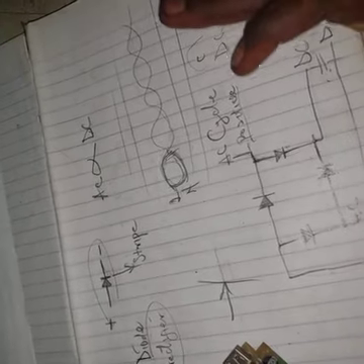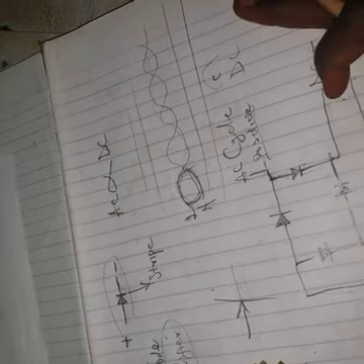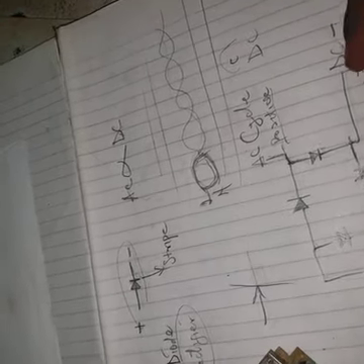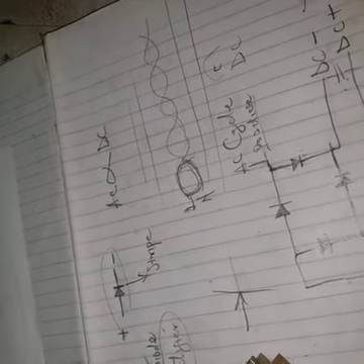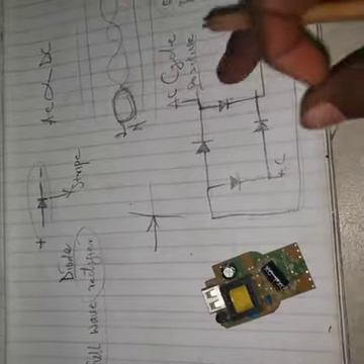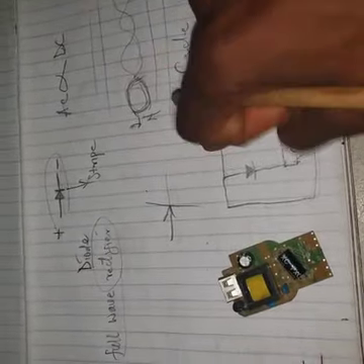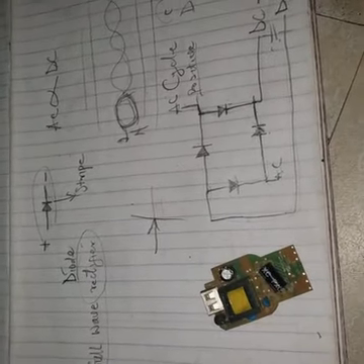When they add capacitors, they will smooth out the waveform. And some might also add voltage regulators so that it will stabilize the DC output. But the main thing is that the diode that we see here is what is being used in order to form a rectifier, what converts AC to DC.